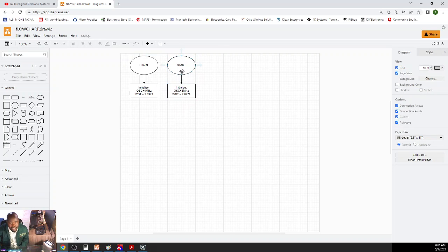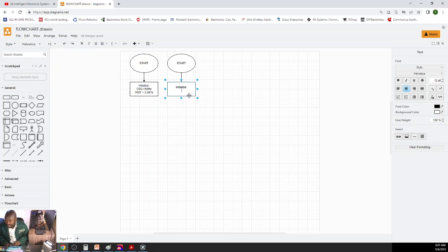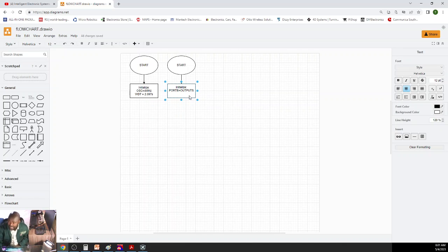We're still going to have origin 00 start, but in this case, at initialize, what is it that we want to do? For the 7-segment, obviously, port B must be outputs, right? And then in our application on the second, RA6 and RA7 are the 2 pins that select which 7-segment is on at a time.